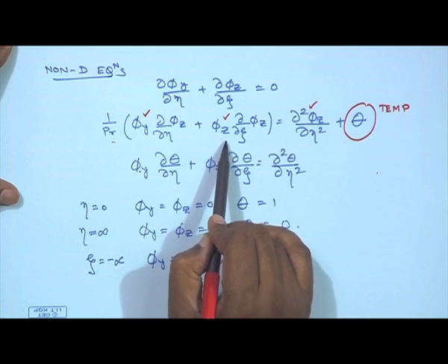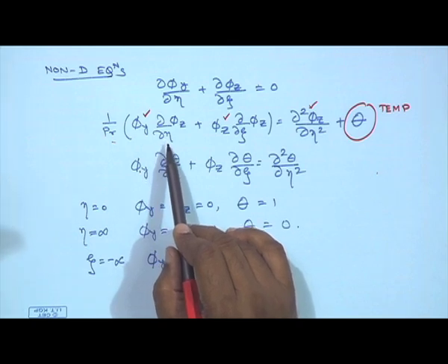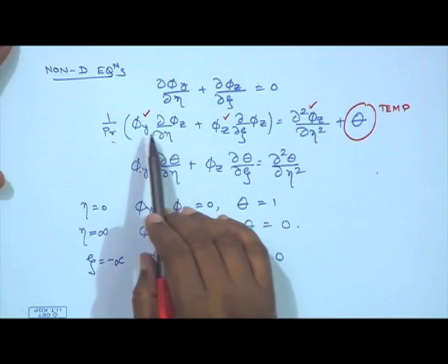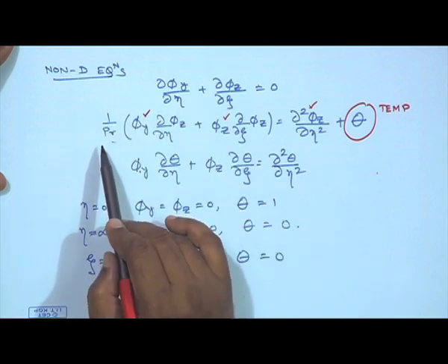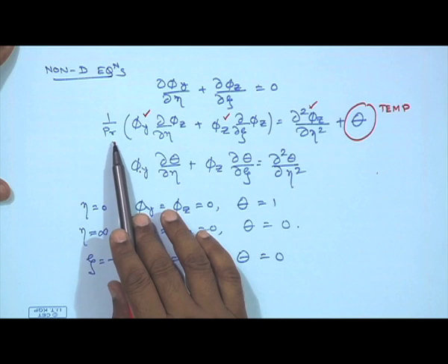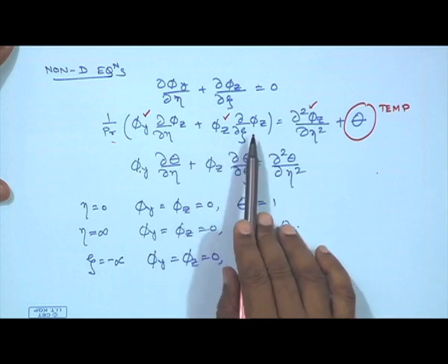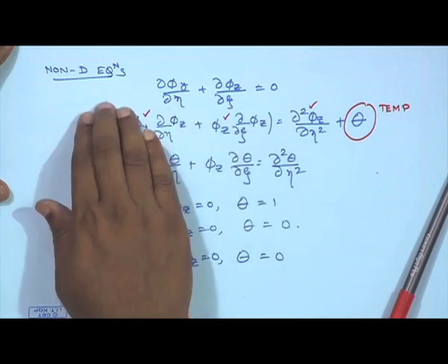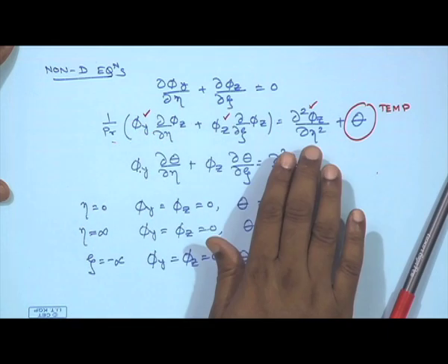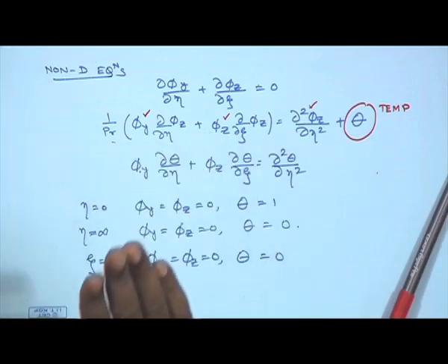In the limiting case, when you have creeping flow, you remember we have studied creeping flow before. If we have creeping flow, then this entire left hand side can be made equal to 0. Here the problem may not be creeping flow, but it is still a slow flow. So, the effect of the left hand side of the Navier-Stokes equation on the final form of the solution should be significantly smaller.